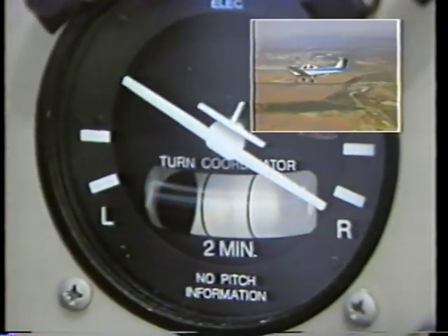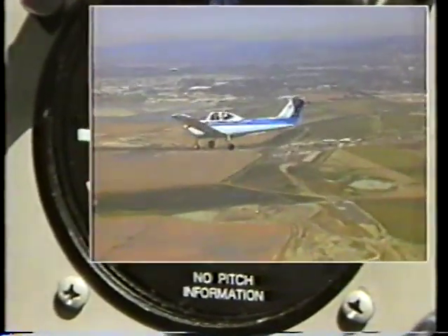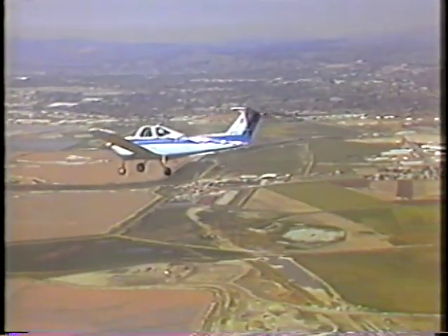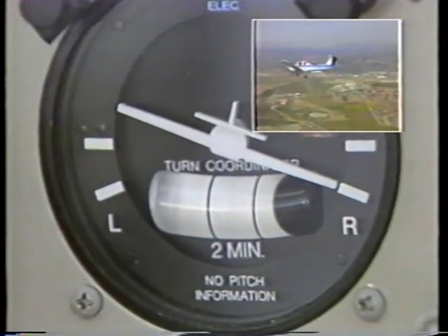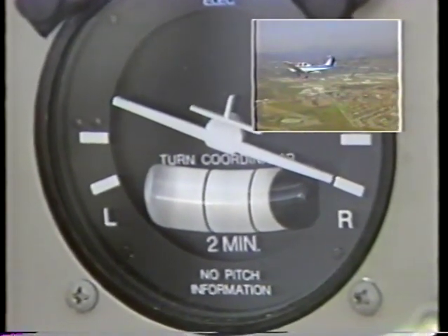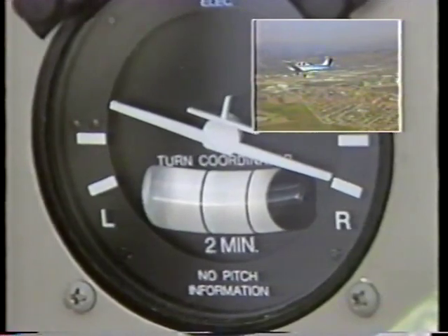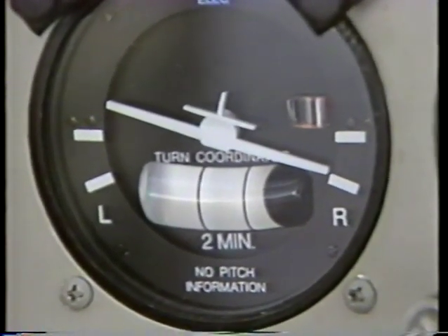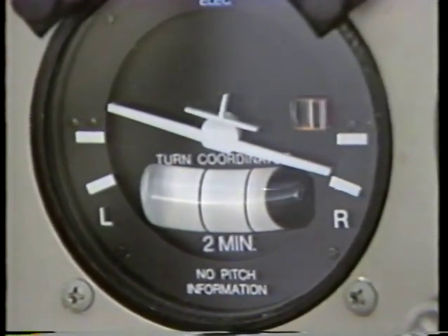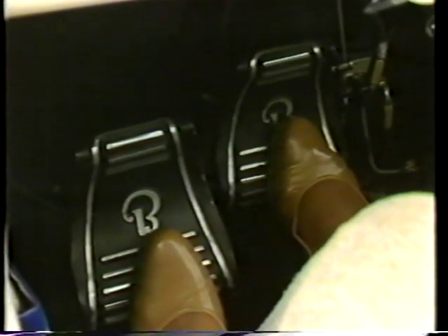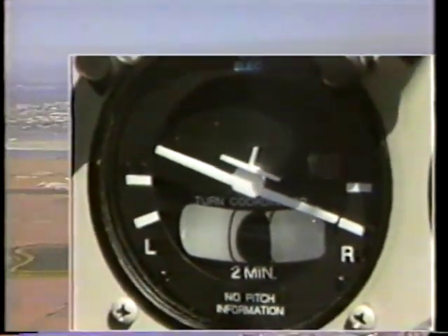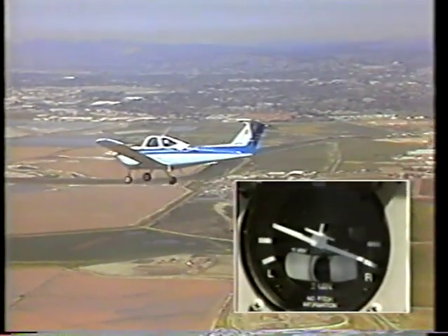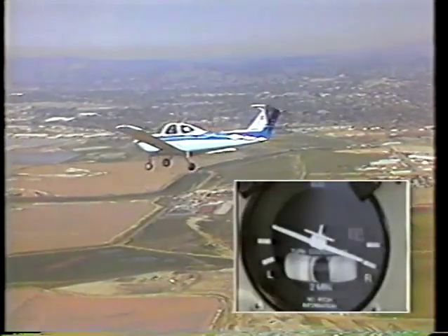The airplane is actually skidding. If too little rudder is used, the ball goes to the inside of the turn and the airplane is slipping. To correct either condition, simply step on the ball until it centers. This means to use the rudder pedal on the side on which the ball is located. But the ideal turn is one where the rudder is used so that the ball never strays from between the index lines.